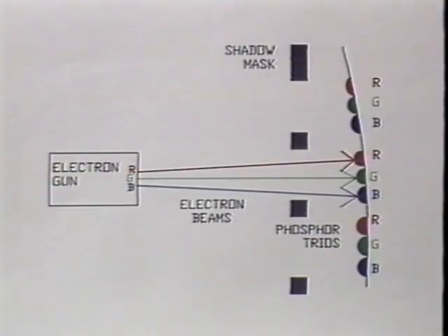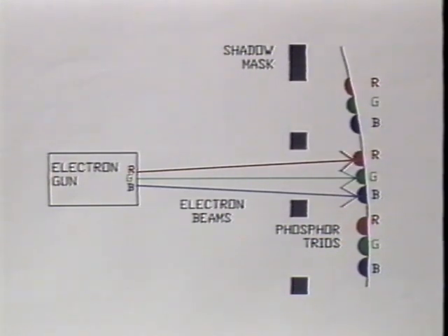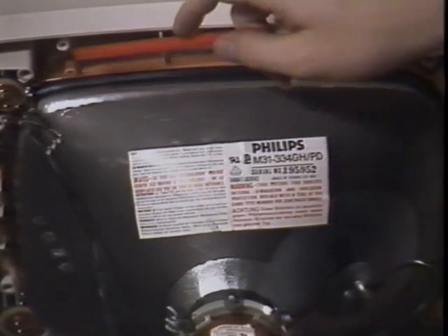There are also 3 electron guns in a color tube, one for each color. A thin grid of material called a shadow mask is placed between the guns and the phosphor to reduce interaction between the colors. A tension band helps prevent the CRT from spraying glass forward in case of an implosion and is epoxied to the rest of the tube. Do not attempt to remove or tamper with the tension band. It may spring off with great force and will leave the CRT unit less safe from implosion.